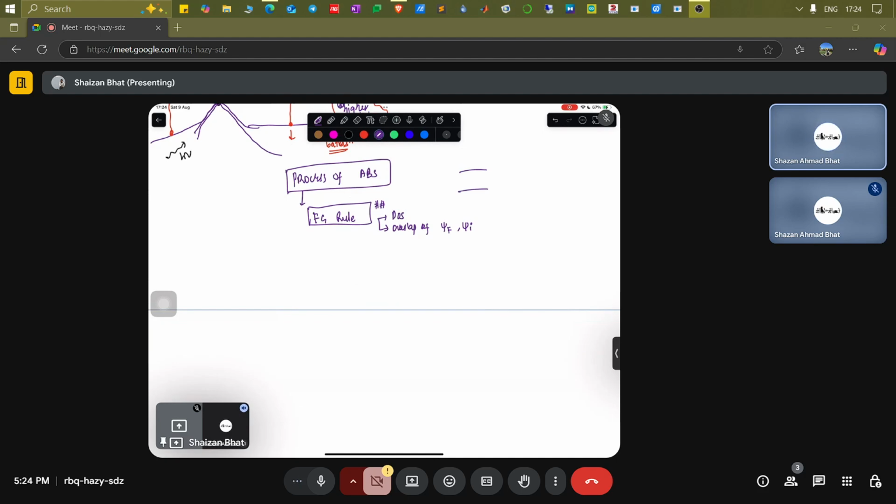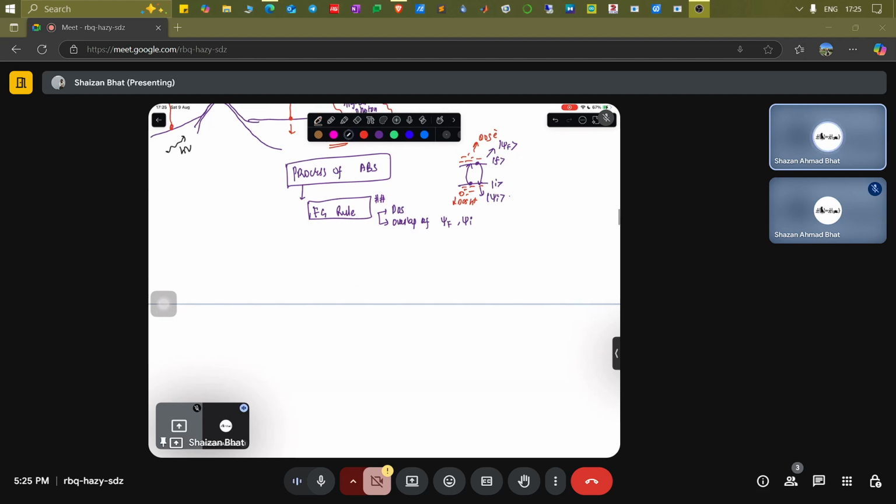Let's say you have two states, this is the initial state and this is the final state. The electron can go from here to here, and the electron can come back. The wave function of the electron here is psi f. The wave function of the electron here is psi i. It is as simple as that. For these two level systems, you can frame some equations which will govern whether the electron is going to absorb a photon or not. Obviously, it will depend upon how many seats are present for the electron, which is the density of states. Similarly, how many seats are present for the holes, which is the density of states for holes. This is for the electrons. So that is what we are going to see.